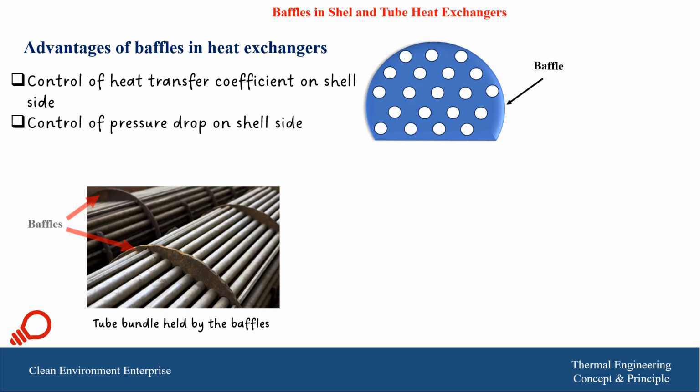So usually these two parameters should arrive at a compromise, because the pressure drop is counted for the power required to run the pumps. And this heat exchanger is only part of a big layout and network of piping systems, valves, and other equipment. So we should minimize the pressure losses inside the heat exchanger.